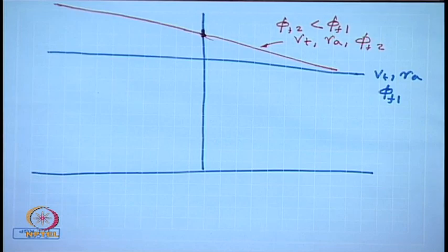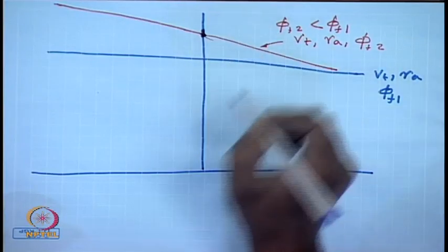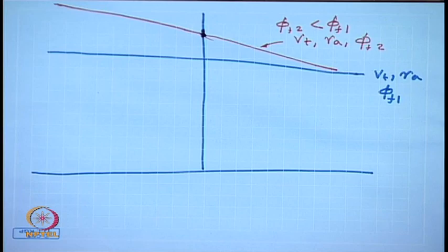It will be interesting to find out how far we can reduce this field flux. In fact, we cannot increase the field flux very much because of saturation. The machines are almost always work at rated flux. We can reduce it, but cannot increase it very much. So, we will consider only decrease of field flux and not increase.